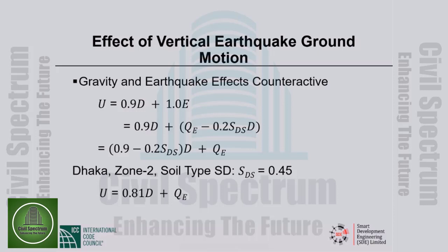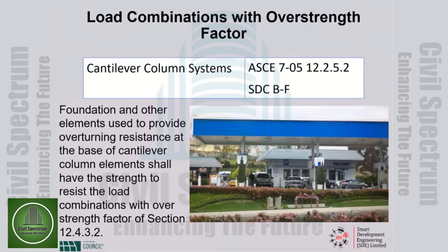We do not have fixed dead load factors in seismic load combinations. The dead load factor is increased in the additive load combination by considering vertically downward earthquake effect, and the dead load factor is decreased in the counteractive load combination by considering vertically upward earthquake effect.